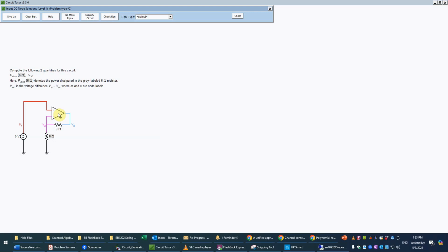However, the gain is in the ideal sense infinite, which means effectively that, since this voltage has to be finite in order to avoid saturating the op amp, this voltage therefore is that finite value divided by an infinite gain, which means it has to be zero. So basically there is effectively a short between the inputs here.